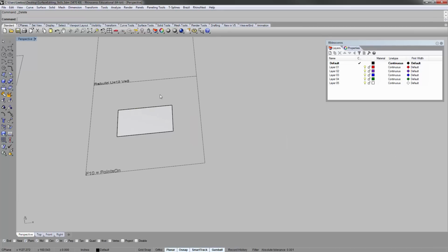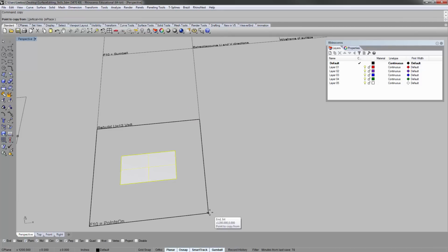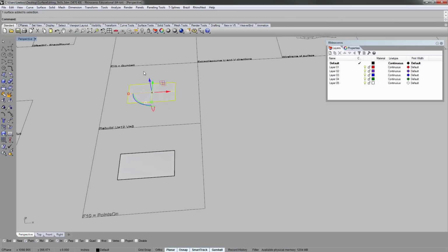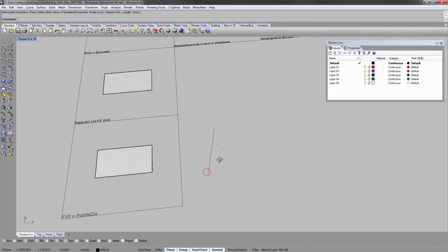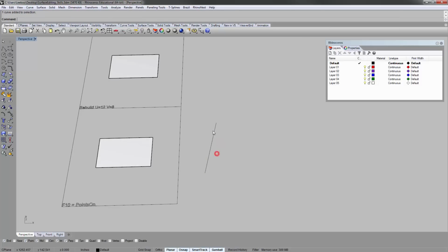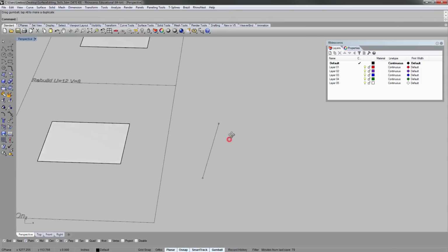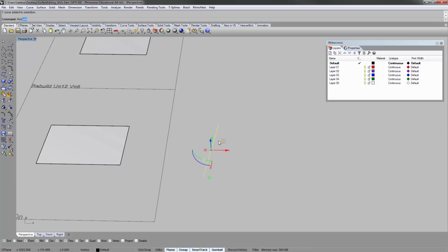Okay? Now, this next command is actually used to reformat, if you will, surfaces to add editability to them. Now I'll show you on the side a simple, normal line like I draw like this, right? This is the same thing. This is a normal line. If I turn the edit points on for this, same thing, F10, I also have only just the 2 edit points. So you'll see me sometimes do this if I need more edit points.